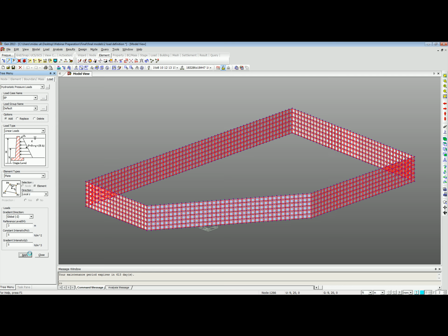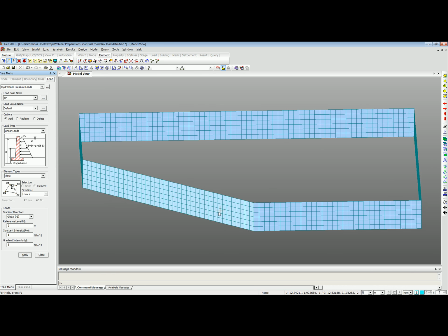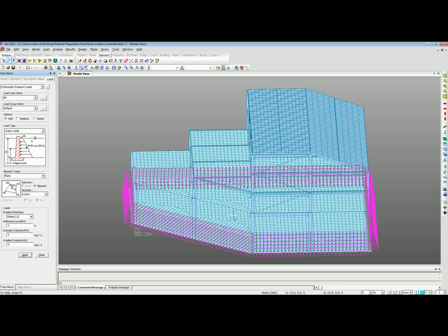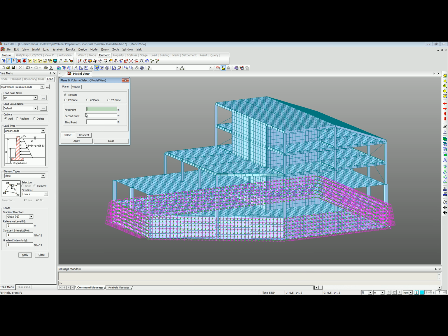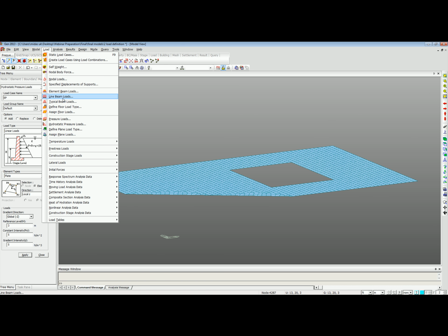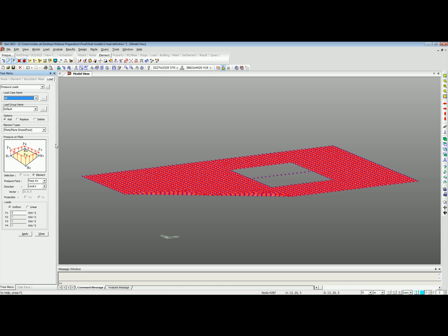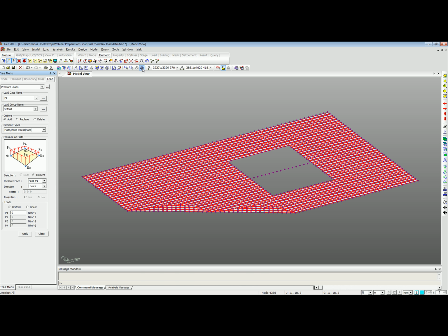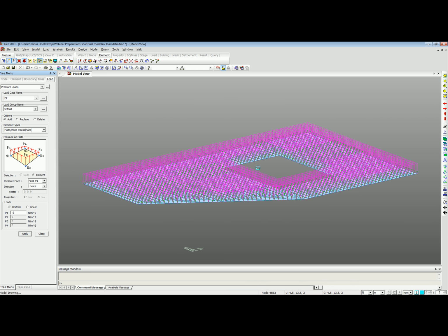Again, if you've got an SI on your desk you can apply that. You can see that it puts the trapezoidal load in for you, so that automatically derives that, just saving you time. Again, we obviously need to apply a force to the slabs, so let me select that by plane. Now it'll automatically define self-weight for you. In this case I'm just going to put a continuous floor load on there, a dead and a live load. Let me apply these. Again, as I said before though, patch loads, line loads, you can put all of them in if you wanted to.